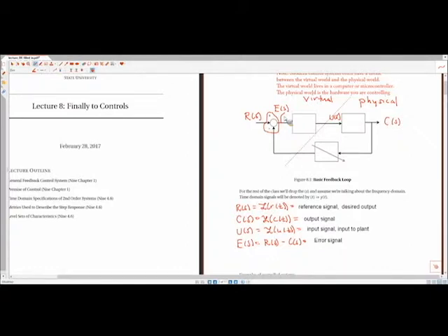So we say that the error signal after the transducer. Which transducer are you talking about? Transducer. Yeah. So that would be the sensed output. We'll get into why we're not going to consider that too much in this class in a second, in terms of the discrepancy between the output and the sensed output. But there is a difference because every measurement system has an artifact associated with it, which I hope you're learning in your measurements class. Any other questions on that idea? Okay.